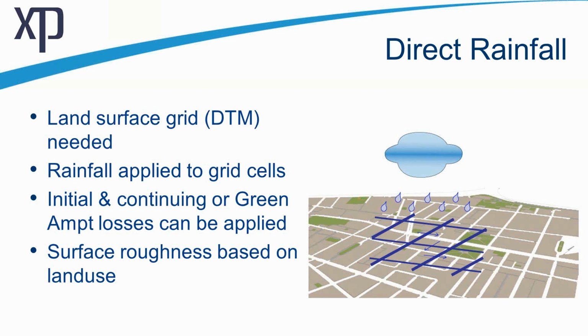Once you've defined your major catchment boundary, you can apply a polygon using a GIS method and apply rainfall directly over your catchment to a digital terrain model, and apply losses based on land use on pure areas, instead of collating those into simple tables of data that you would do in a more traditional sense. And surface roughness also needs to be defined based on a GIS environment.